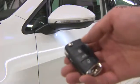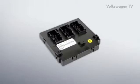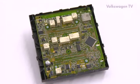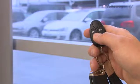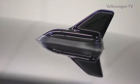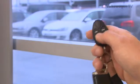The onboard supply control unit is the receiver for the central locking remote control. The aerial is either integrated into the wiring harness or part of the control unit. The remote control signals for the auxiliary heater are received by the roof aerial and transmitted to the radio receiver. As soon as the command has been accepted, positive feedback is passed to the remote control.